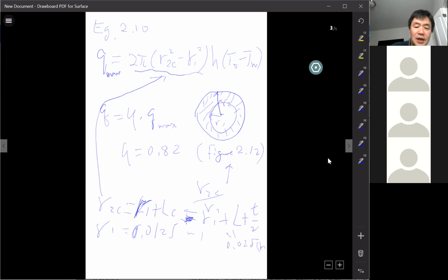You got the ratio, then you can use the plot. Okay, by the way, for the plot you probably also need to calculate ML. In order to use figure 2.12, you need to know the bottom axis, right? Look at the bottom axis: LC to the 3/2 power times the square root of H over K AM.